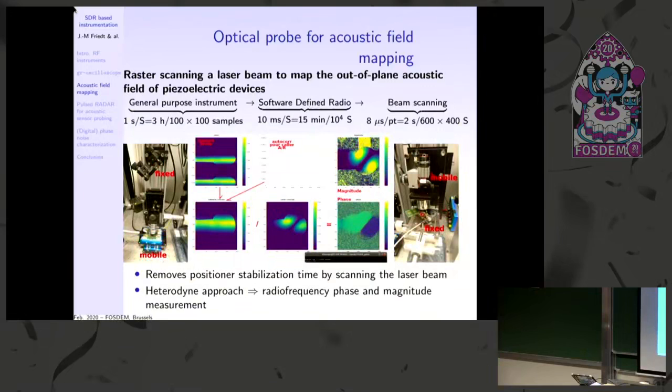And there you see that you take the best out of the streaming of software-defined radio, because now you're not wasting, you're just limited by the data stream for the software-defined radio. Notice that we started with 10,000 seconds per measurement, and we reached 2 seconds per measurement. This is what I call what you could not do without software-defined radio.